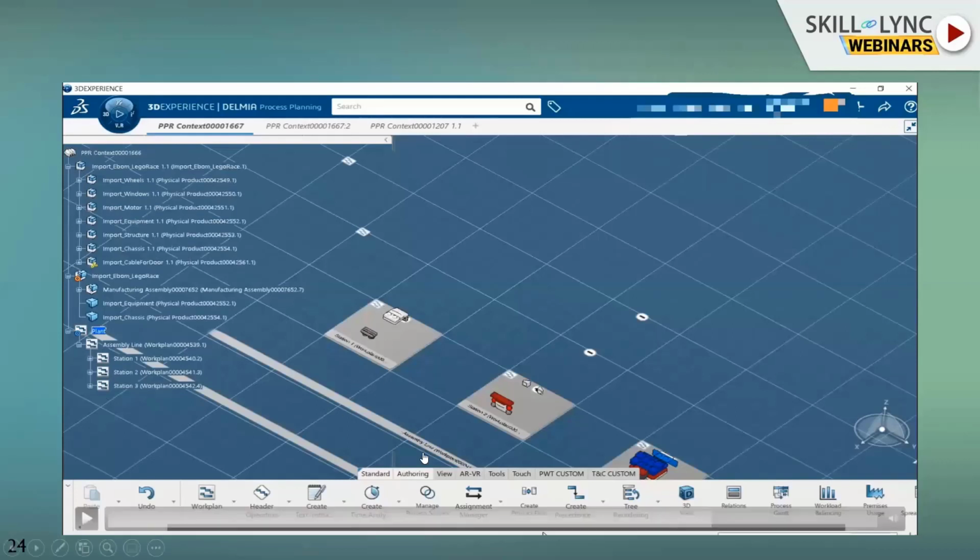For that, you have what is called a mannequin simulation, where you can actually place a human being here and try to see if his hand is reaching there, his screwdriver is reaching there or not. Those kinds of simulations you can do. You could do clash and contact simulations, because in the automotive industry there are different standards saying that you cannot place something very close to each other, like say 5 distance has to be maintained between two particular parts. Those kinds of things you can analyze, you can learn about different stuff like how to create product flows, how to streamline your product flow, and then you can see what is called a Gantt chart.